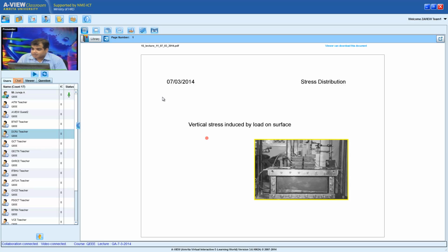It covers how the vertical stress is distributed in ground. So if you have a case where the ground is loaded and you're looking at any stress distribution, we are mainly interested in vertical stress distribution. So this section will only focus on vertical stress, that too for an elastic material. Our focus is elastic material, and you would be surprised that if you use such an assumption for soils, you're not really too wrong.